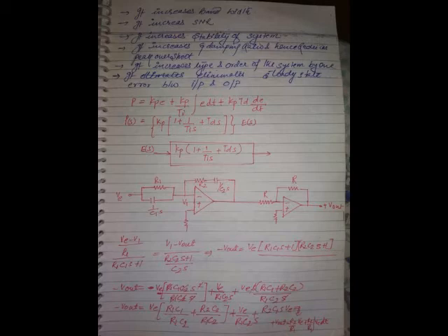This controller is capable of improving the speed of response of the system. Speed of response is defined in terms of rise time. So what is the effect of this controller on rise time? Rise time will reduce, so the response is becoming faster. Whatever specifications you are writing are applicable for only D as well as phase lead.